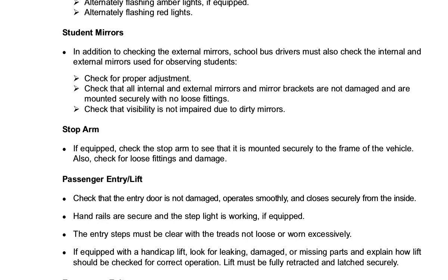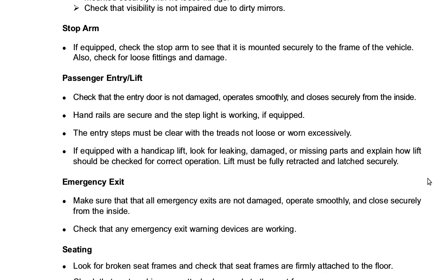Stop arm. If equipped, check the stop arm to see that it is mounted securely to the frame of the vehicle. Also check for loose fittings and damage.